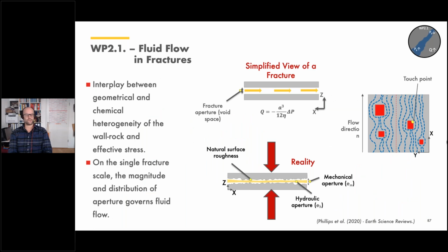We then looked at roughness. I mentioned before that typically in modeling, fracture flow is looked at as kind of a parallel plate system with a very simple flow relationship. But the reality, of course, looks different, and the reality has roughness, and this parallel plate concept might not be relevant, especially for the more rough fracture, stiff kind of rocks where we see high roughness. Next slide, please.